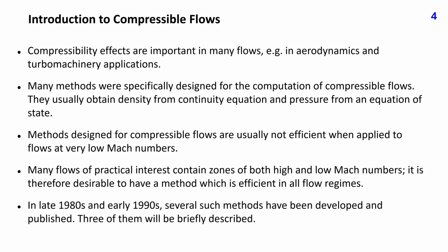Compressibility effects are important in many flows, for example, in aerodynamics and turbomachinery applications. Many methods were specifically designed for the computation of compressible flows. They usually obtain density from the continuity equation and pressure from an equation of state. Methods designed for compressible flows are usually not efficient when applied to flows at very low Mach numbers.